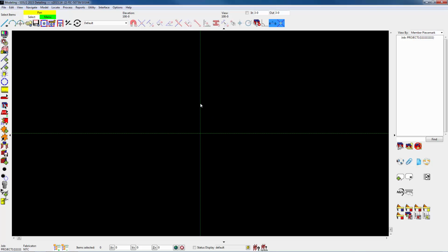So now we have 2 construction lines on the screen, and we need to add more construction lines. So looking at our sheet S1, the first thing we're going to do is, again, I set column line A, which is going horizontal on your drawing and horizontal on my screen here. I'm going to use that as 0, 0. So this line is at 0.